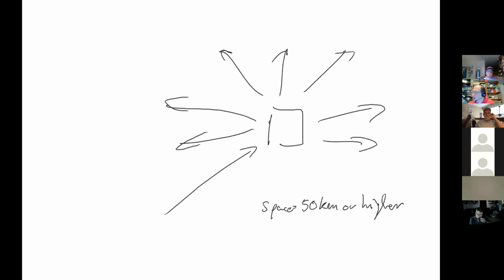It's mode UV, so it's UHF upward and VHF downward. If you send a signal up on UHF, it will come down on VHF. That's known as mode UV. It's a UV repeater, and that's actually 200 miles up in the air, whipping around the earth.